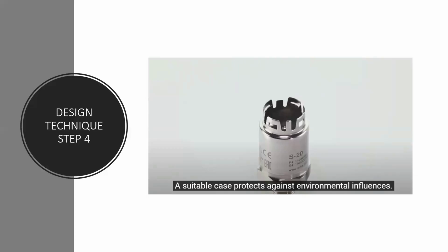For example, the kind of sensors we are going to use in a steam boiler must be able to resist high temperature, and we have to factor in using a case that can accommodate temperatures over 150 to 200 degrees Celsius. For such, we also can limit the use of material.